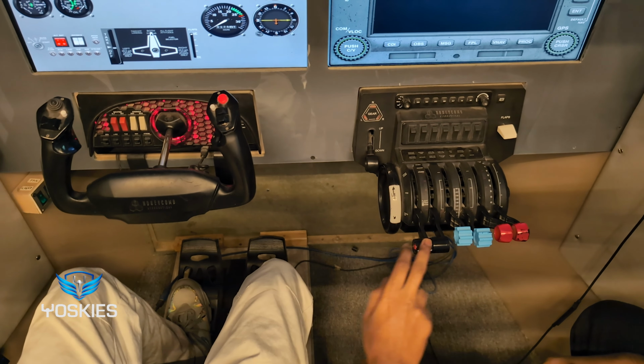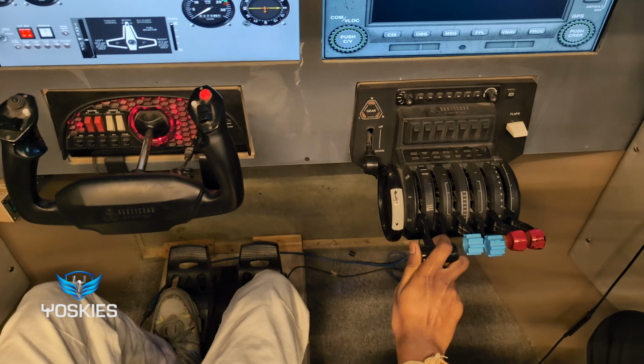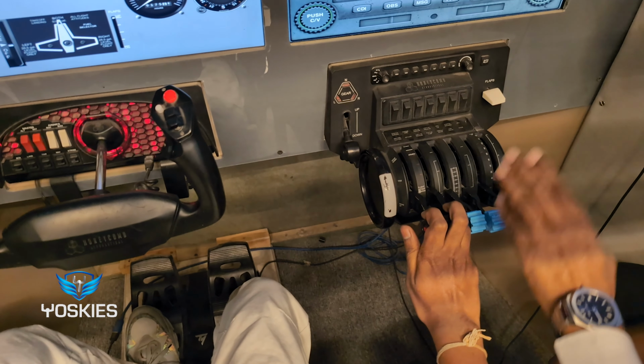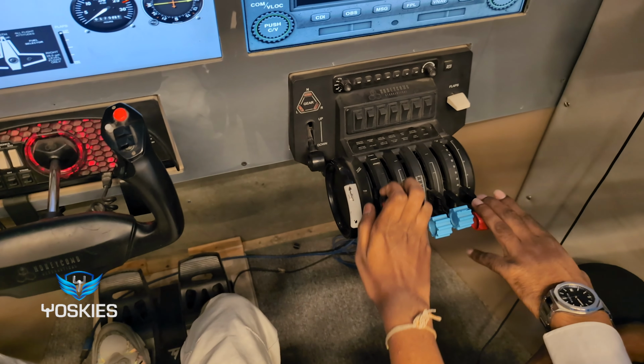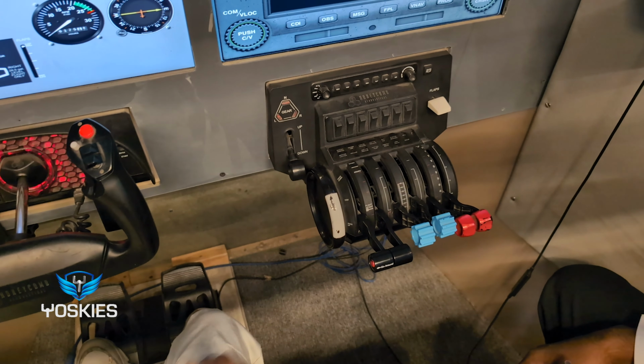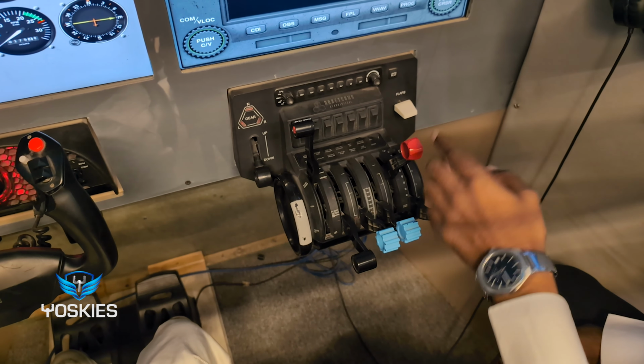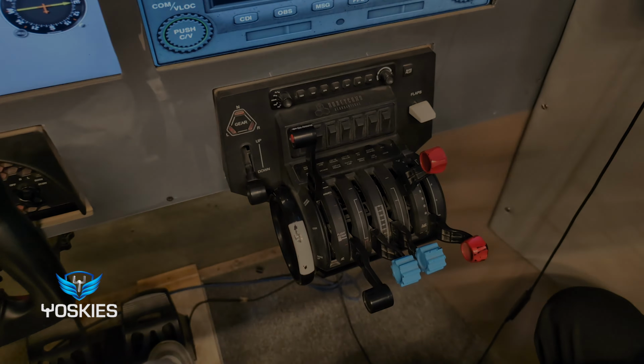So this is your throttle quadrant. Since we fly multiple aircraft in the same setup, we have two throttles, and for feathering we use this, and we've got two mixture controls also. But since the Cessna is a single engine aircraft, we will use one throttle and one mixture control, which allows the fuel supply to the engine.